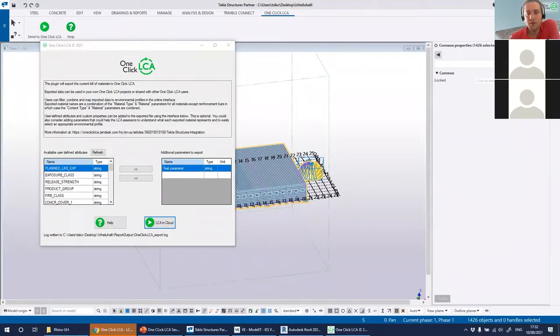And of course, I would also mention Carbon Designer. So if there are any elements that are very generic, you have no idea what they are, or you think you need too much time to find out what these are, and they are relatively minor elements, you could also exclude them from your Revit model or other model, upload everything else, and just complete the model with the use of Carbon Designer.